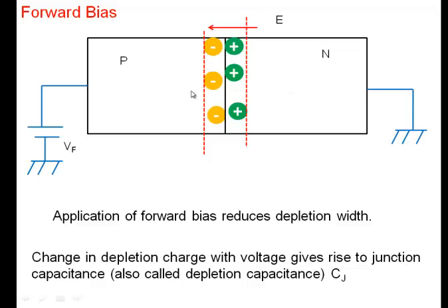And what happens? As the current becomes large, more and more voltage gets dropped in this P region and this N region. Earlier, most of the voltage was dropping across the junction. That was the bottleneck. But as the current increases, this is no longer the bottleneck that much, and the voltage starts to drop in the P region and in the N region. So increasingly more voltage gets dropped in P and N. When you say, suppose I do apply 1 volt to the diode, well, 1 volt is not going to drop across the junction. Most of that excess voltage is going to drop in P and N, and the voltage across the junction may still be 0.1 volt.